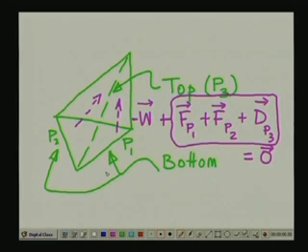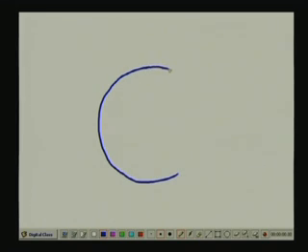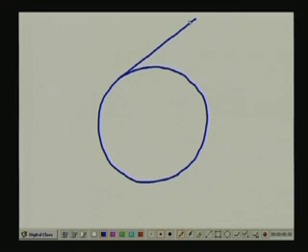Now, if you find that the wedge is going to be unstable, then what do you do? Let's illustrate this problem using a simpler configuration. Let's revert back to the problem of the two joint sets striking parallel to the tunnel alignment, and let's assume that, based on the principle of mechanics, we have assessed that the wedge which is cross hatched with a purple color there is unstable.